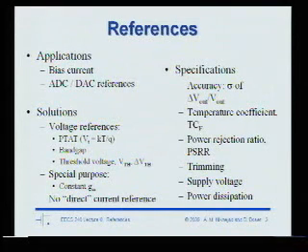In particular, we're going to focus on 3 voltage references: PTAT, proportional to absolute temperature; band gap reference, which we're going to go through very quickly; and other kinds of references like VBE references and threshold references. One thing that's interesting about references is that all the good references out there are voltage references. Okay?